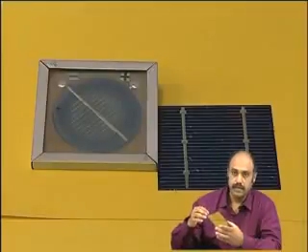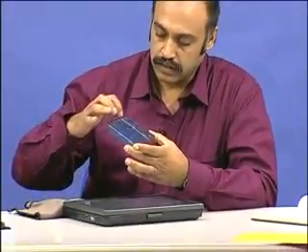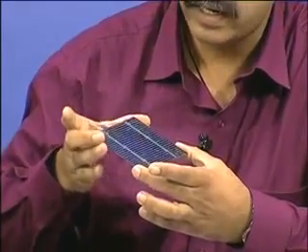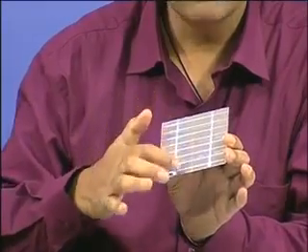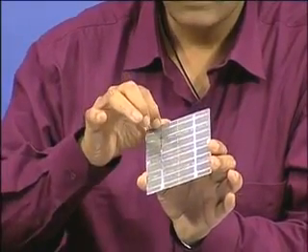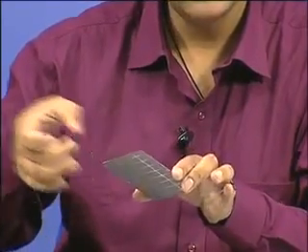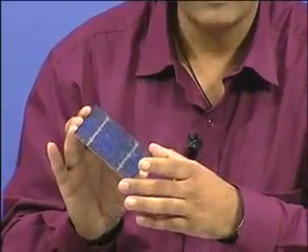The top layer would be an n-type layer, and the sun rays will fall on this, and on this there are metallizations which are soldered on one layer, and on the back side also you will see the metallization, so that we can solder one lead on this and one lead on this side and take it off, and that would be the two terminals of the photovoltaic cell.